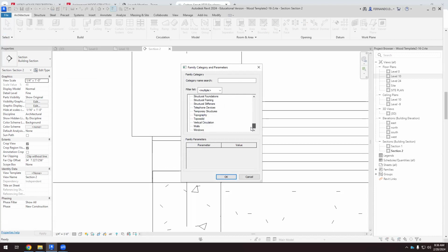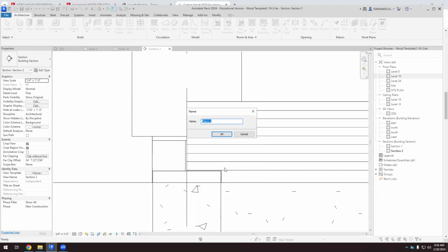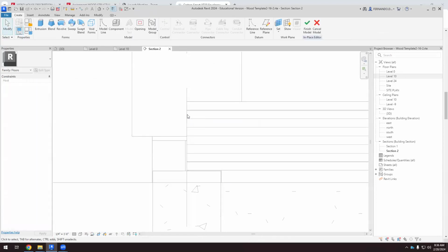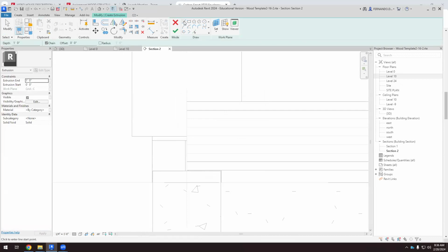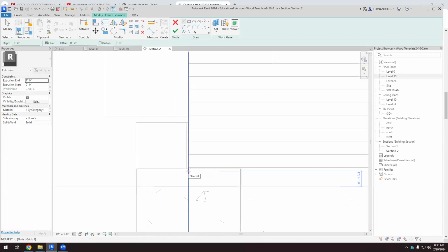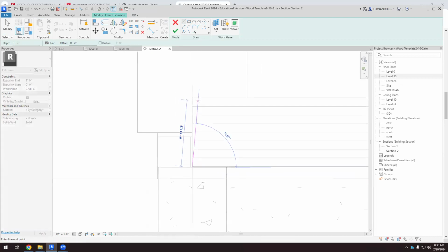Okay, so if I'm working with the floor, I'm going to use floors because that's an element that belongs to the floor. I'm going to use extrusion. I'm going to pick, I think grid C will be better. Before I picked grid A, so now grid C is the right option. And I'm going to create a thermal insulating material starting here and then there. I'm going to create a 4-inch thermal insulation here and there.